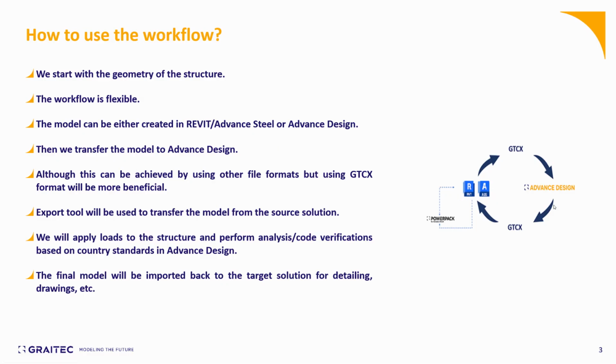Through this workflow, all of the loads, even if you have defined some loads in Revit, will also be transferred inside Advanced Design. And coming back from Advanced Design inside Revit, all of the internal forces in your beams, columns and slabs, as well as, if you have done a concrete design, all of the required rebar areas will be transferred inside Revit.